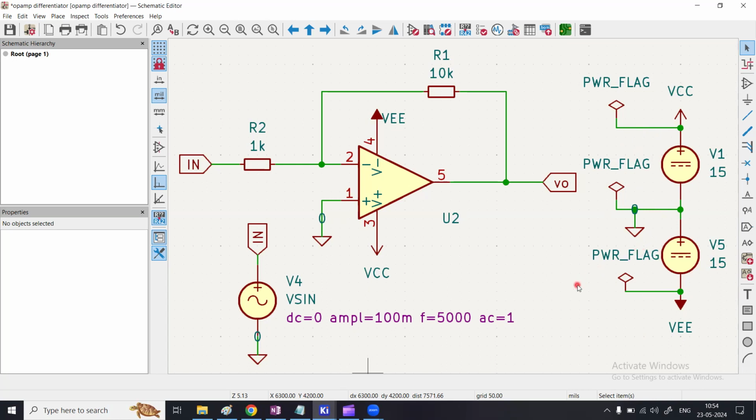When you design the PCB, when you design the schematic, it is often the practice to apply supply decoupling capacitors, usually 1 microfarad, from these nodes with respect to the source potential ground, to reduce the noise. Then there are many components that contribute to the overall noise of the circuit, which we can measure at the output. That is called the output noise of the circuit.